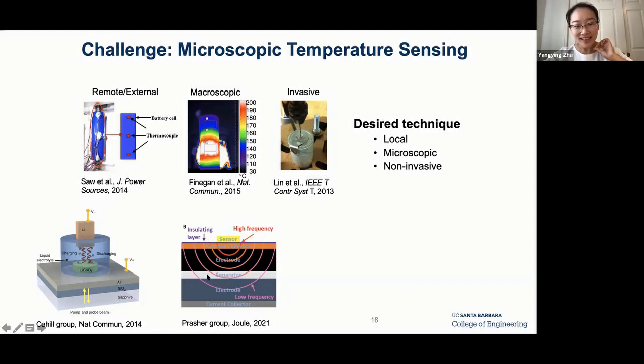By measuring the thermal conductivity of the graphite anode, they are able to know the distribution of the heterogeneity of the lithiation process inside the graphite, which is extremely important because we want the battery to be uniformly charged or discharged. If you have heterogeneity, that is almost always the first reason that can cause lithium plating or any defect to occur. So this is really clever.